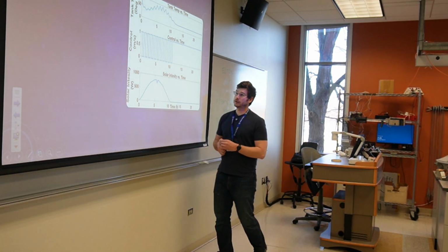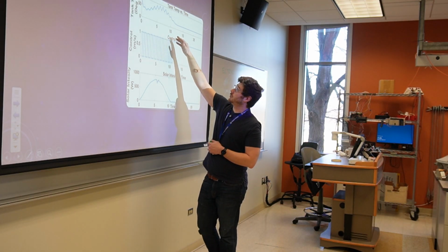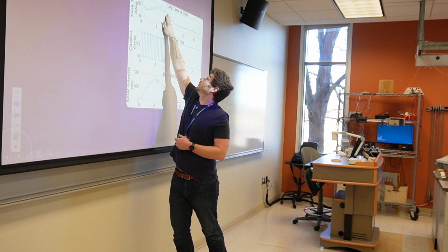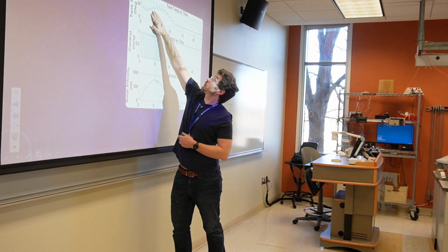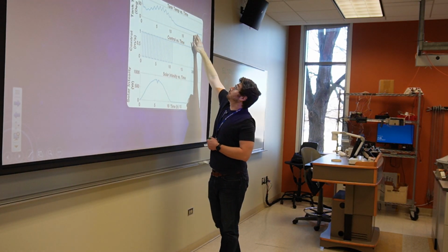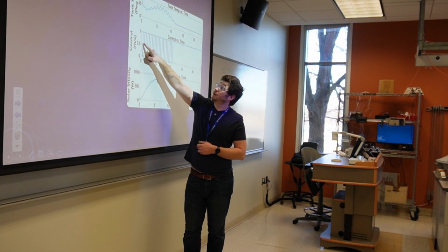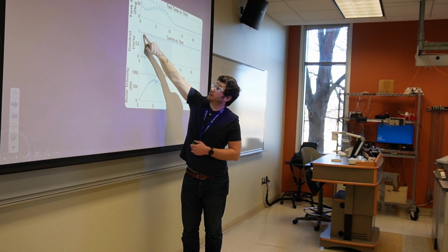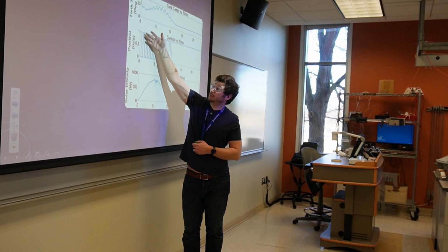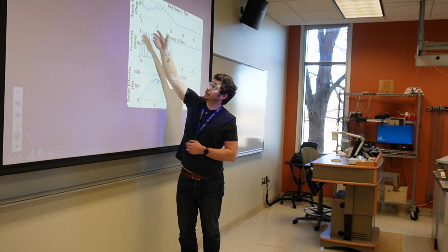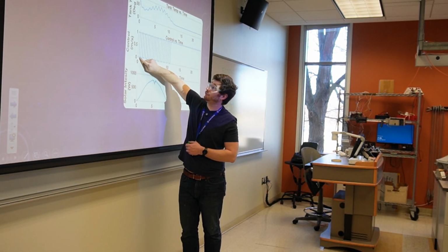Okay, so here what we're seeing is, for example, if we want to try to regulate our temperature, this is the actual tank temperature that we're reading here. How does that tank temperature respond when we turn our heater on and off? So this is what I was talking about, our process control variable, where we're turning our heater on, which is 1, or turning it off, which is 0.